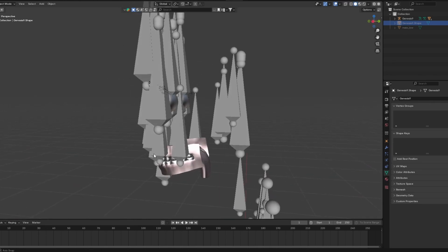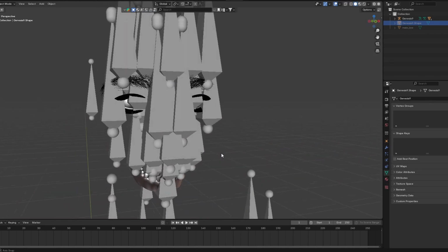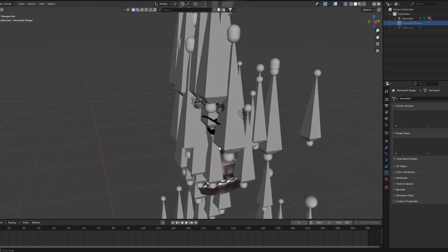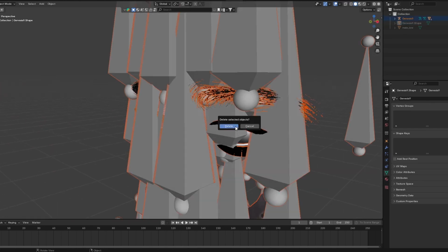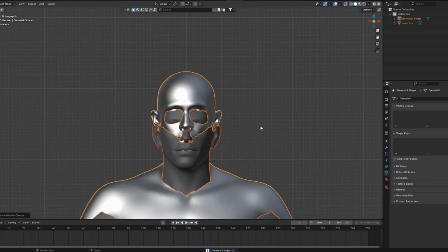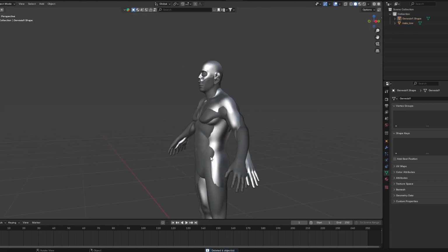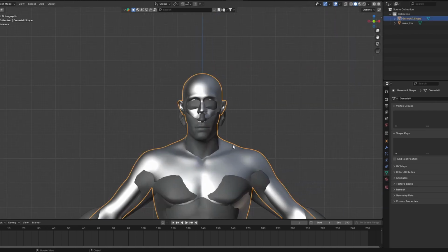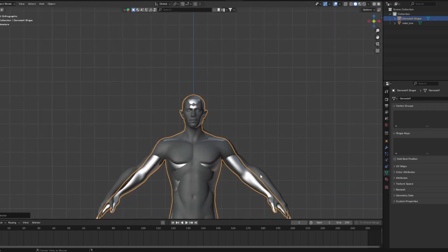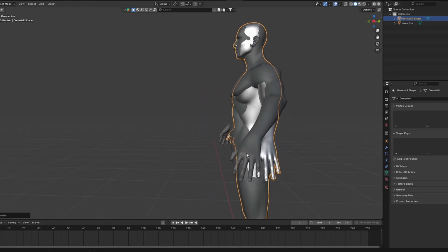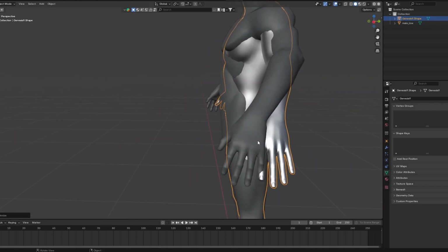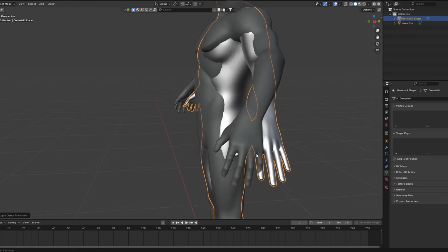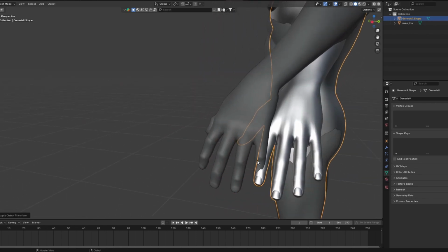So over here, probably for this tutorial, I'm not going to need all these parts. So I'll just delete everything and unhide everything again. So I have this. Great. Now the size doesn't matter here. The important thing that you need to take note of is where the fingers are placed. They need to be approximately close to each other. I mean every single finger. Otherwise, when we proceed to the next step, we'll get a lot of errors.